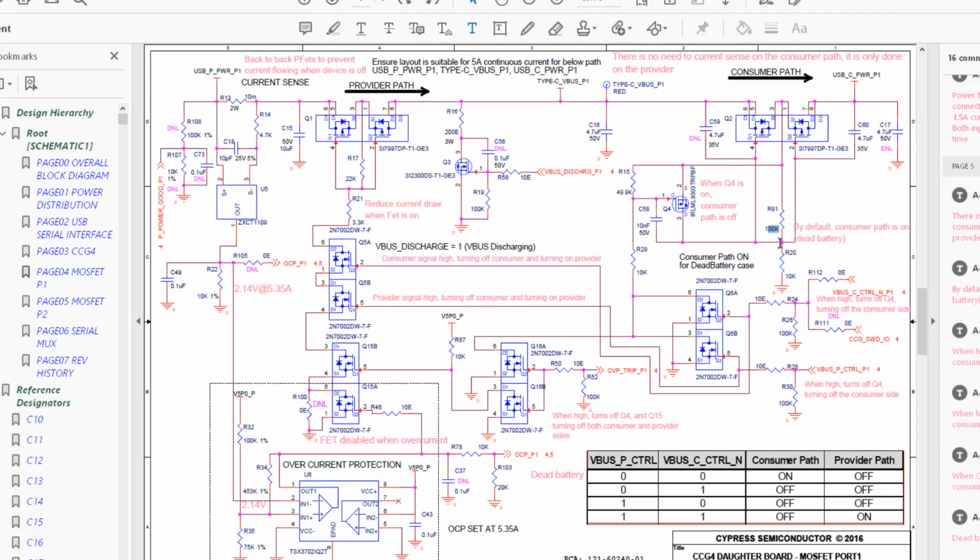There is a 10K resistor to ground, but you'll still get 20 volts here. So when this circuitry is on, you've got 20 volts divided by 10K in current, at least, minus all the other bits and bobs that are kicking around in this circuit board. And this isn't the most power optimal design. Right, so this is how they're turning off.